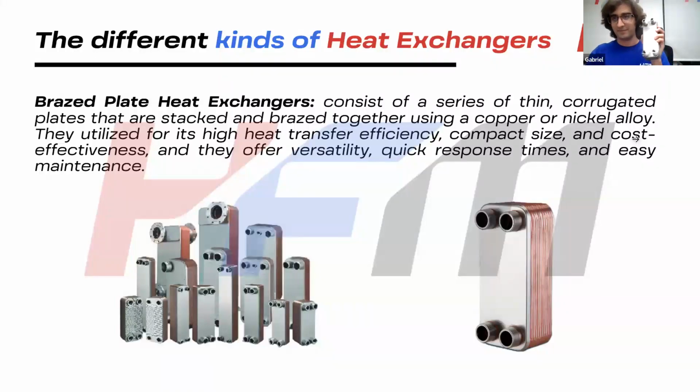Here I have a brazed plate heat exchanger. It's not a miniature now, as you can see how compact they are in comparison to the other that is sometimes bigger than me. So one of the fluids is going to enter here. We have the same system of plates, the same principle. One of them is going to go out from this. Meanwhile, the other one is going to enter here and go out from this. So the same process is going to happen between the plates. The fluids are not going to mix. They're going to go in a counterflow, and they're going to exchange the thermal energy. In other words, they're going to exchange heat.